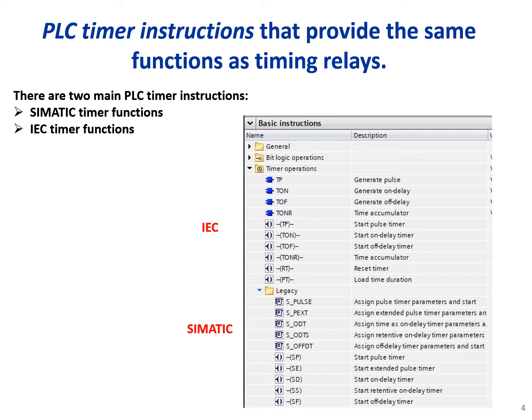discussed in the introduction to the TIA lecture, you have noticed that for any instruction we could have legacy SIMATIC ones and IEC ones. The IEC ones are very similar to ones that you could find also in CODESYS, because CODESYS is based on the IEC standard, and SIMATIC are specific to TIA and they only work with the Siemens PLCs.